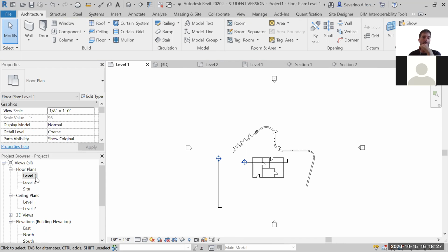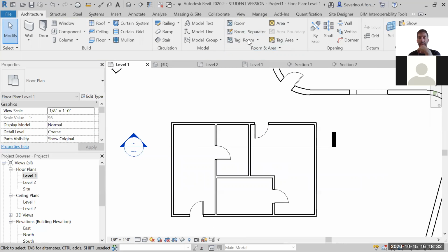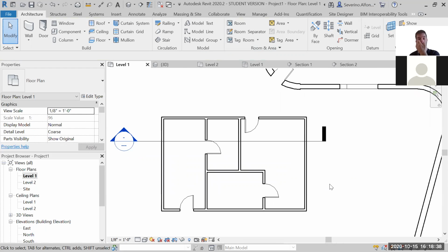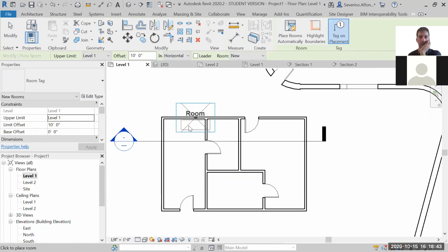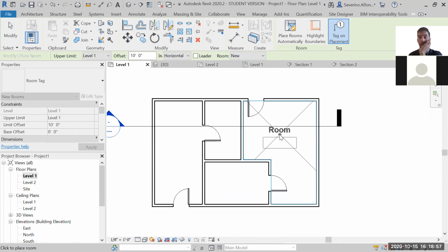One thing that I haven't talked about, because it's more about construction documents, is very useful, is this, the room and area options. Okay, I'm just going to go briefly because it's not what I want you to do, but it might be useful for studio. If you click on room, you can insert your mouse inside of any room from a floor plan. And notice how this X-ray detects in blue the perimeter of the room. That means that it's naming and understanding the perimeter of that room. And you can do that with as many rooms as you have.